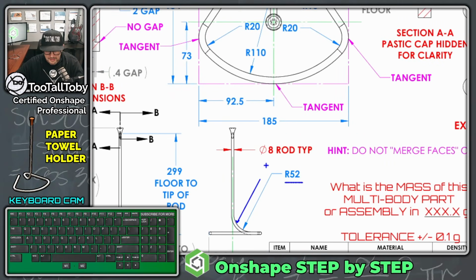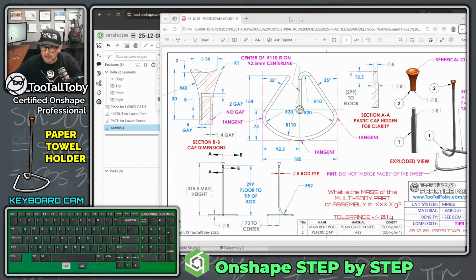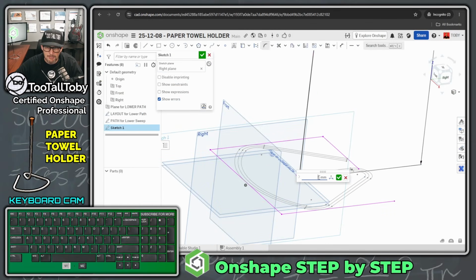But if we think about it again, that's the inside bend radius. So really what this needs to be is hashtag half wire plus 52. Because we want to add 1/2 wire thickness to this radius so that it's 52 at the inside bend, even though we're actually drawing the center line of our sweep. So we're going to do this using our variables again. We're going to come in here to this box, get rid of this 5, get rid of the mm, so there's nothing in that box.